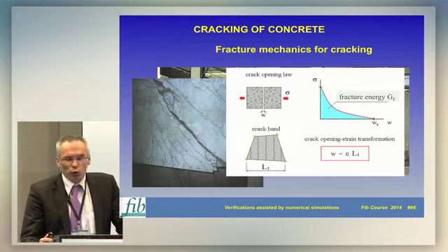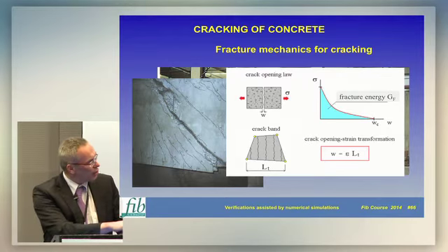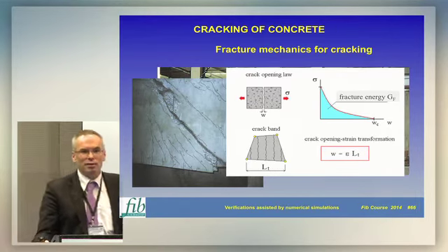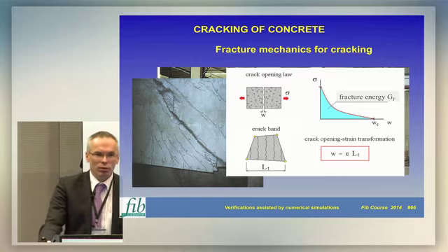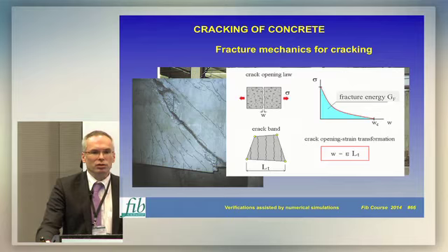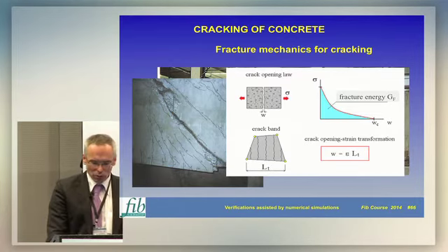The other issue we have to keep in mind is that if you come to reinforced concrete and use large elements, let's say you model the containment, where the element size may be 1 meter, and it's reinforced, then the assumption that there is a single crack inside one finite element is not true anymore. So this also should be somehow addressed by the software, that once it is reinforced, we need to make this equation a little bit more complicated.